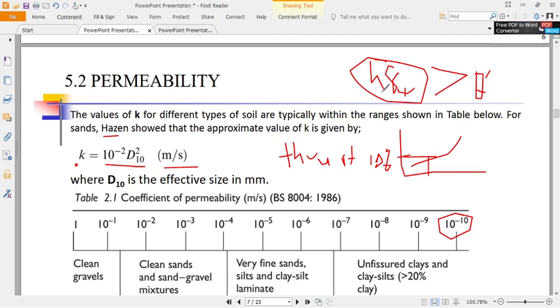Water will start coming out, because the hydrostatic pressure is much greater than the effective stress. This is good for design. If you are designing and filling into a swamp, you need to determine how much fill you should put, so that you don't have water rising through the fill. To determine this X, the amount of fill to put back, or the fill material.